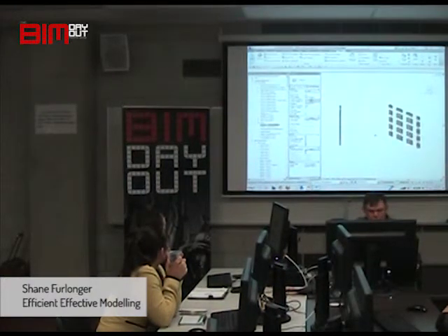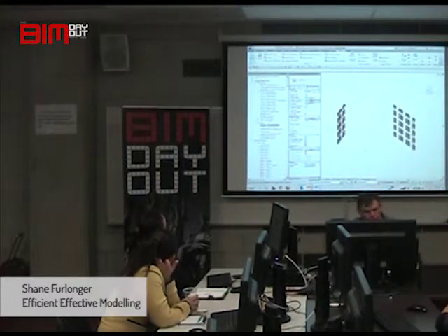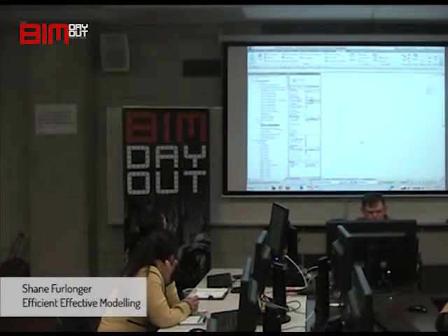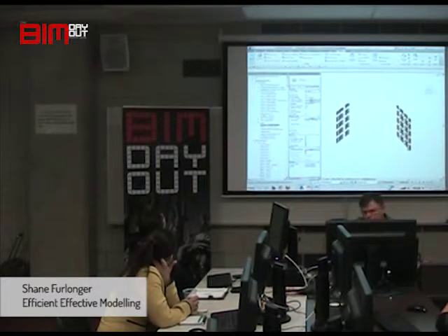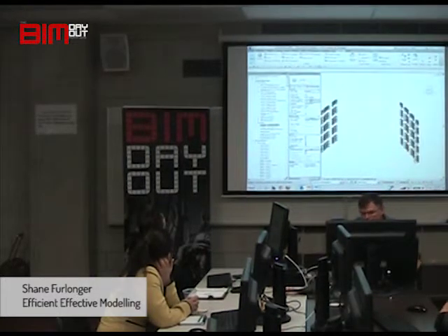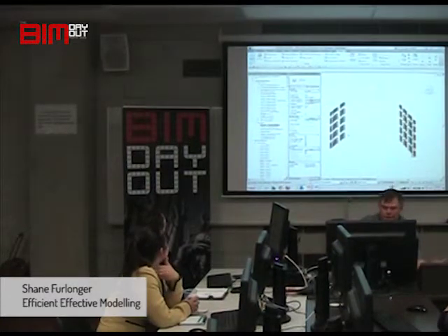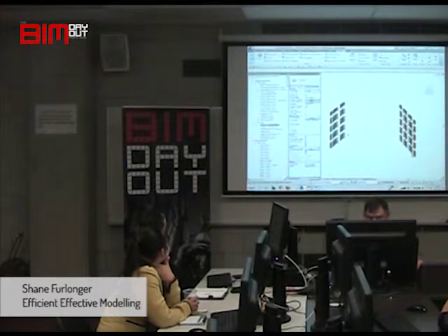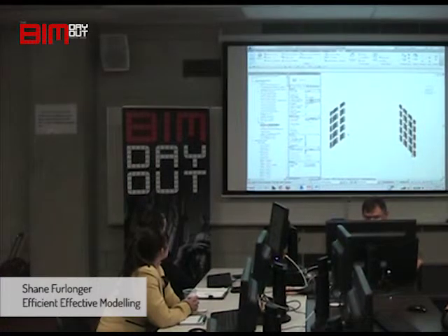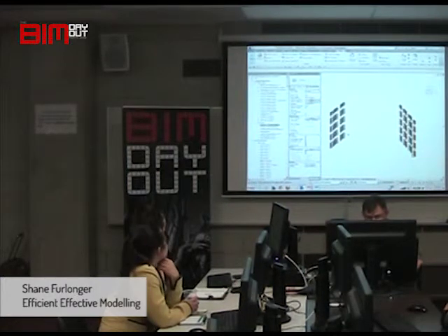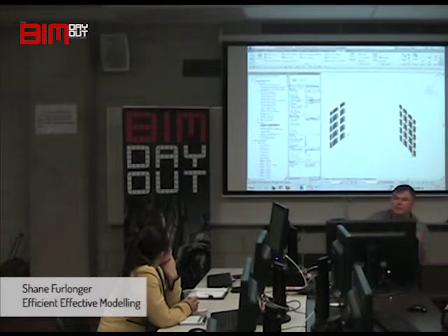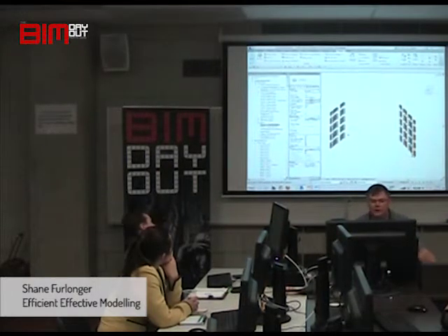This was some balcony framing that needed to go on the building, and because it was changing and evolving on a regular basis, I wanted it outside the model in a way. So what I did was I copied everything into this legend phase and worked on it here until I got it the way I wanted it, and then I made a group out of it, and used those groups back in the model so that if I needed to adjust them they would adjust in both places.